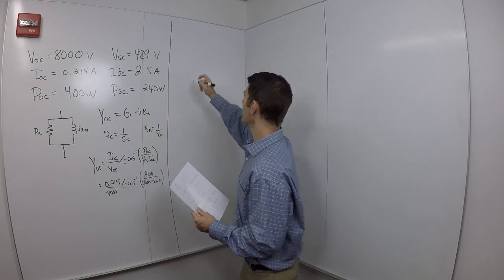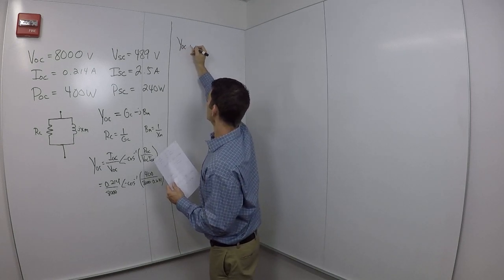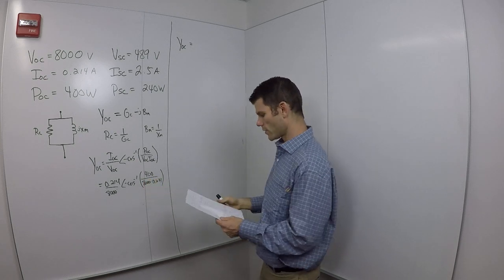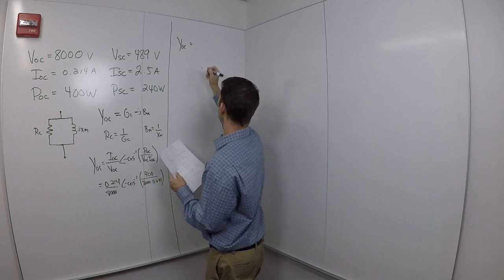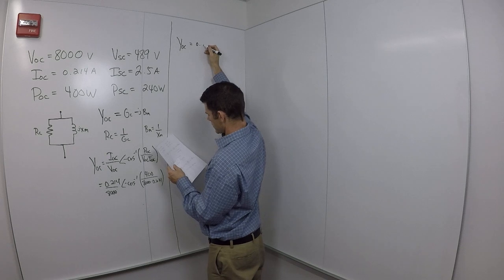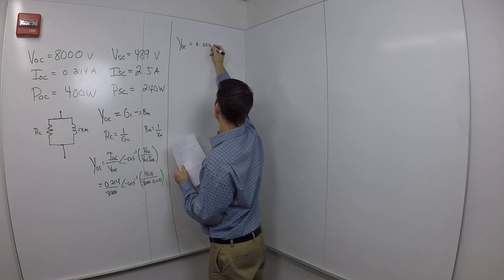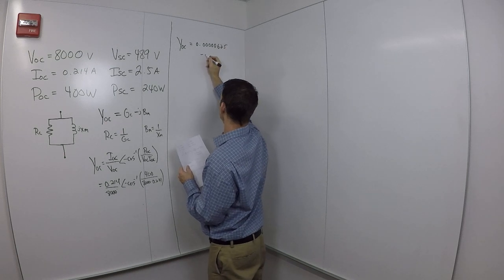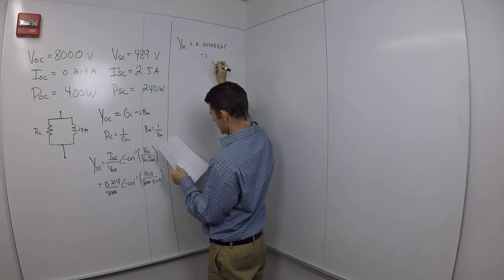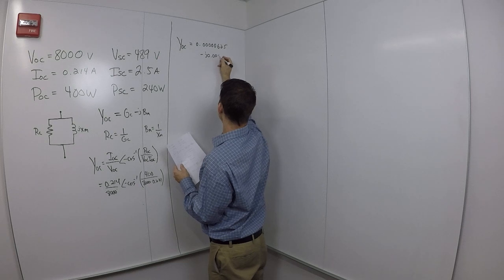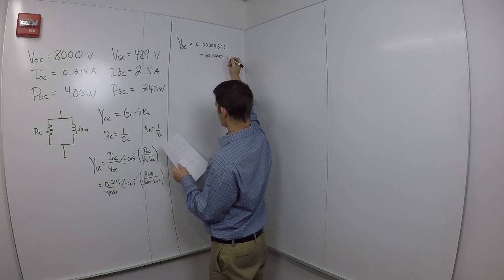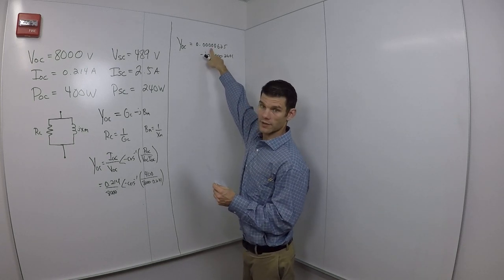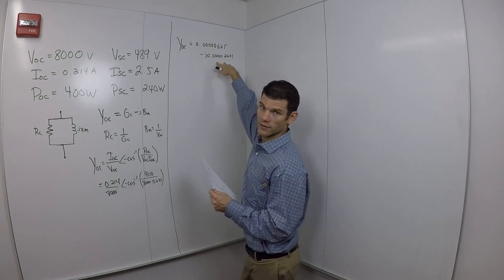Okay, now when I calculate that out, the best way to do this is calculate this in rectangular components. And when you do that, you get 0.50625 for the real component minus J, and then you have 0.402601. Okay? So this component right here is the conductance. This component right here is the susceptance.